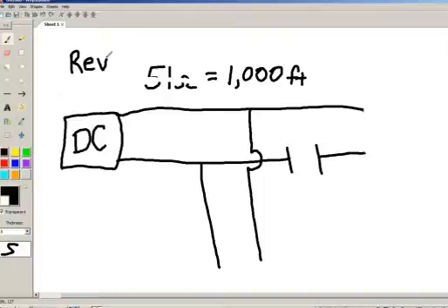Well, what that REV switch actually did to the meter was reverse the polarity of the battery. I tell telephone people that I train we only have two types of battery to deal with. One is DC. It's got a constant polarity. It flows current in one direction. The other one's a little bit unpredictable. First it has one polarity, then it has another. We call it AC. So when I'm kicking with that reversing switch, believe it or not, I'm putting a real crude AC signal on the line. Now, what's your point, Jeff?